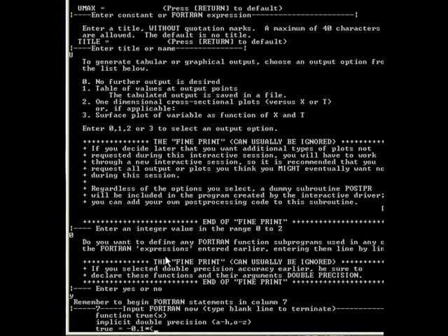It's just basically fourth derivative of U equals the constant. And so you take, integrate 4 times and apply the boundary conditions, and you can easily find the solution. But in the book, it's given as minus 0.1 times x to the 4th power divided by 24, minus L, which is 2.5 times x cubed divided by 6, plus L square times x squared divided by 4.